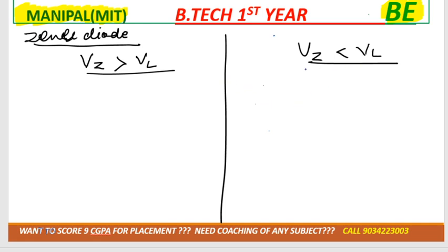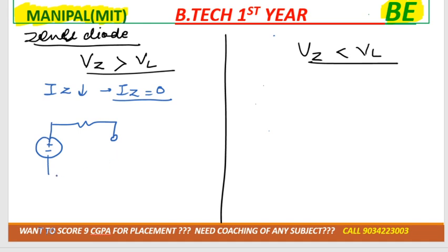Okay, suppose in the first case Vz is greater, then that means Iz is less. Yes or no? So if Iz is less, we can consider Iz equal to 0. If Iz is equal to 0, as you know, no current is flowing through the Zener diode.